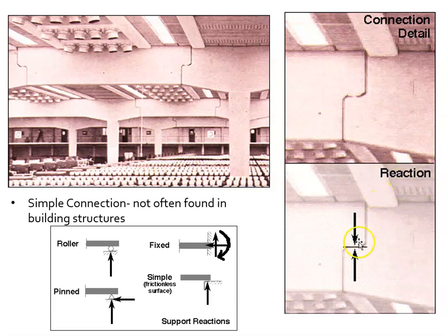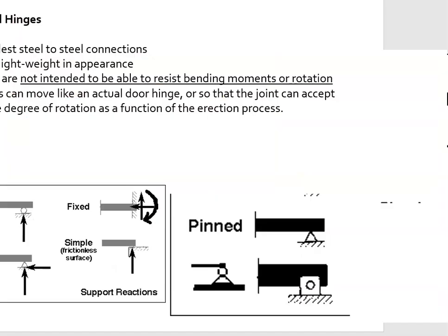So this is the reaction. This is the connection between the two, right? Where all the force, all the load from above, the snow from above, is accumulated here in this middle piece, and then it has to get transferred right there at that support. And then it comes over to the column and gets transferred right here. Okay, not too common though.